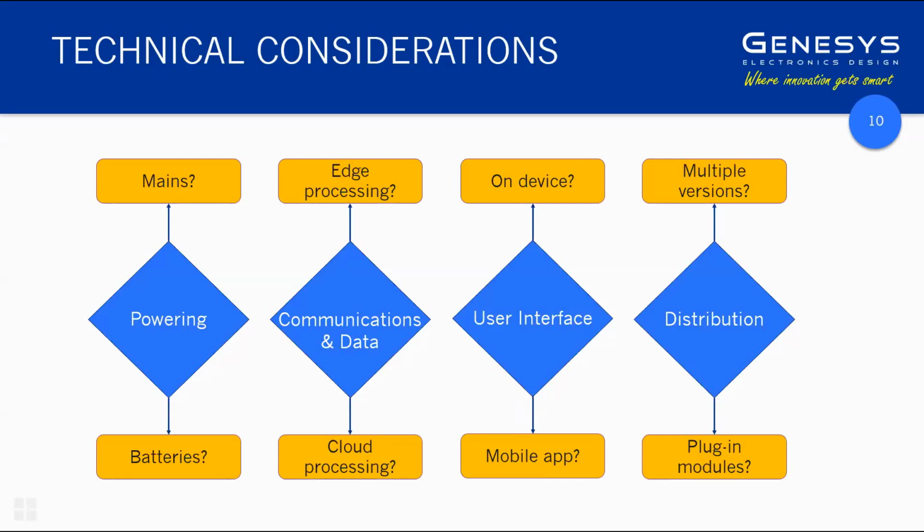And there's also a topic for another day, which is regulatory compliance of medical device software. There is a hidden trap that if you are using a commercial grade platform, you then have to consider the software on it. There's a thing called SOUP, software of unknown provenance, which is a huge minefield. So if you're developing a safety critical device, you may well consider having the primary user interface, an LCD screen, on the device so that you can fully control and develop the software to be compliant with the medical standard for the software and not have a problem arising from third-party software of unknown provenance.